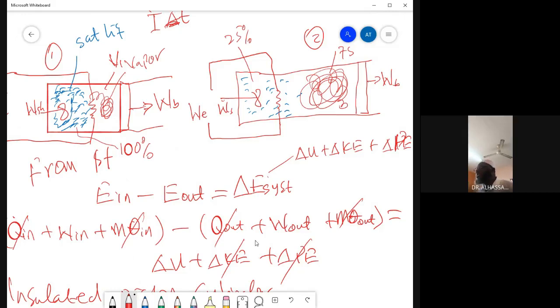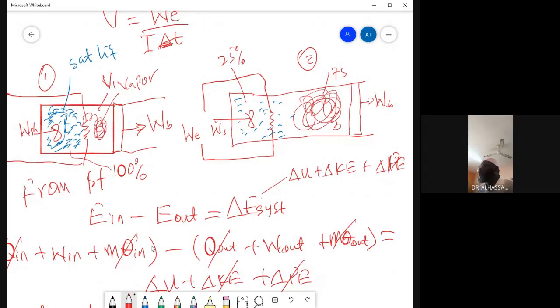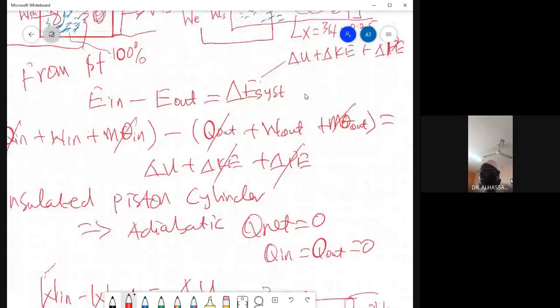Okay, so 75% of the vapor. 75%. And this constitutes 3/4 of the vapor. Okay, so if this is 3/4, then this is going to be 1/4. So here, what they want to tell you is that the value for x, which is the vapor fraction, x equals 3 divided by 4, which is 0.75. That's the value for x. Okay, so it's very important that we notice this.